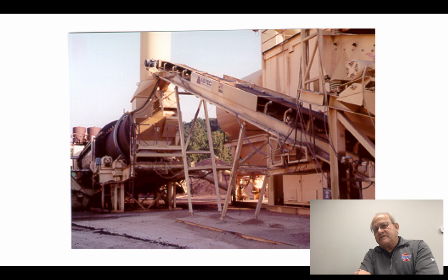There's also on this conveyor a signal generator that gives us a basis of time, because you can't use real time, because sometimes these conveyors, as you put more of a load on them, you're running heavy, they'll slow down a little bit or speed up a little bit when you slow down the plant. So we actually use a speed indicator on the conveyor belt itself so we can take the weight versus the time to do a ton per hour calculation. This is all done within the computer on the control system on the plant.